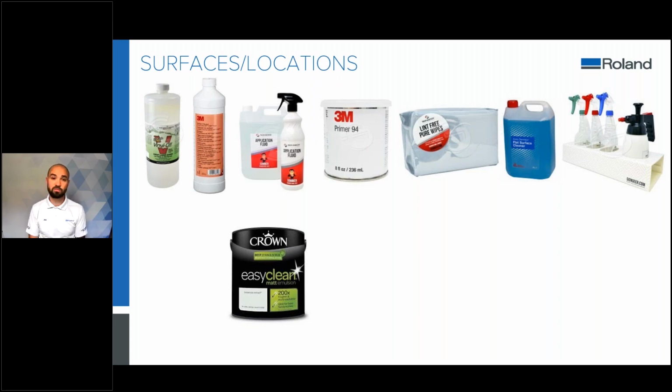If you've got a portion of your materials, maybe send that to the customer or apply that a week or so before you're going to be applying your graphic, and check whether it's going to peel off from the wall. You would want paints to probably cure or fully dry. It depends on the different type of paint, but probably around 30 days before applying your graphic. It does depend on the type of paint, but the only way to really know is to do a test.